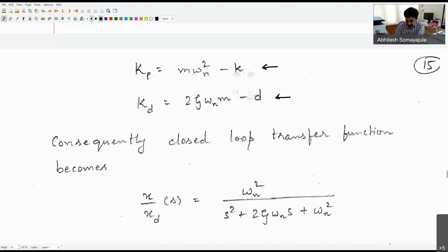I may know the mass and the stiffness very easily. Many times I may not know the damping precisely. So that's why the damping can be approximated using the methods we just discussed. And then you are choosing your poles to be at a certain location and applying these methodologies to determine your controller gains. It's a rule of thumb to get your controller gains, but please make sure to understand that once you determine your controller gains, you have to actually do the simulation with a high fidelity model to verify that your control system is working fine, right?